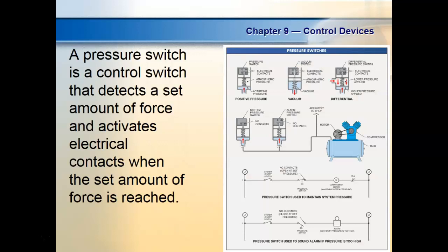Pressure switch. These are not solid state pressure switches. We have a solid state pressure switch that we use, but it senses both what we call pressures and vacuums. Basically, a vacuum is any pressure that's below atmospheric pressure. What's standard atmospheric pressure? Anybody know? Surely y'all heard it. 14.7, close, yeah. Of course, that varies with altitude. It also varies with temperature. But that's the average pressure at sea level.